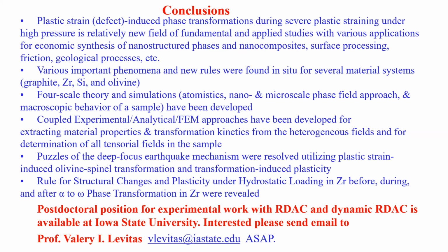But then when we do phase field modeling, we apply this 1.3 GPa to our sample, which is full of dislocations, and local stresses at the tip of a dislocation pileup can be 60 GPa. And this is not only pressure, but shear stresses. You know, the problem is why macroscopic thermodynamics does not work. Macroscopic shear stress is limited by macroscopic yield strength, which is several GPa, and its contribution in comparison with high pressure is small, tenths of a percent.